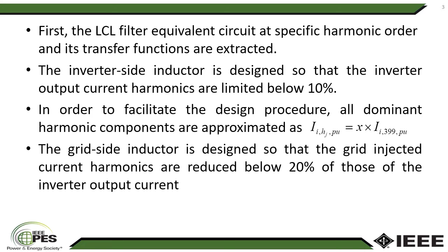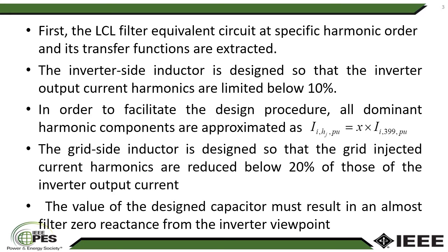The grid side inductor is designed so that the harmonics of the grid injected current are reduced below 20% of those of the inverter output current. Also, the value of the designed capacitor must result in an almost zero filter reactance from the inverter viewpoint.